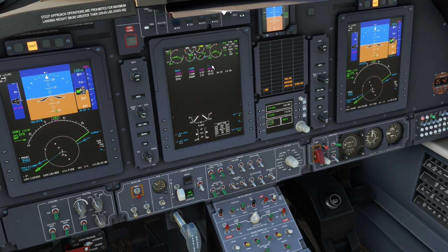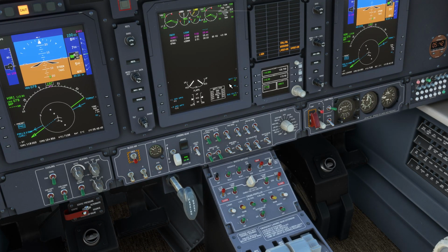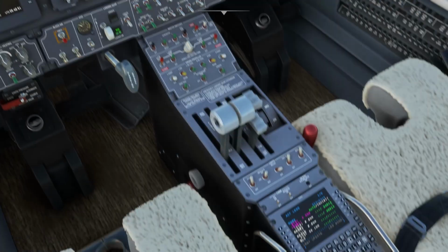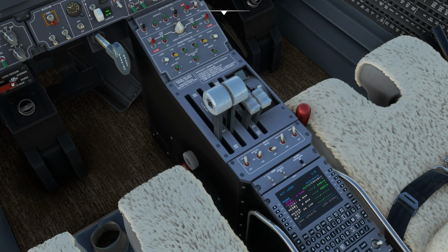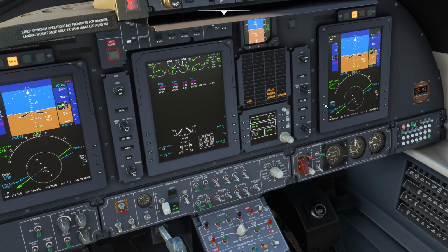Once the gauges are stable, we'll move the right condition lever to ground idle again. Sorry, not ground idle, FTR. Right, so these are stable, so move it down. Don't worry about going to the cut off part, it doesn't go that far, you need to separately click on it and pull it down.